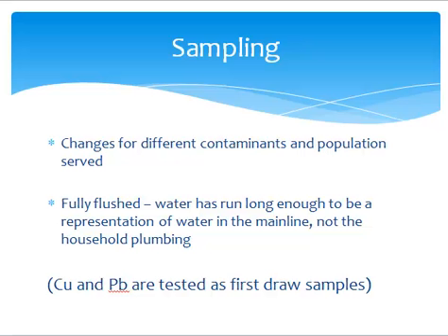When and how often a municipal source collects water samples is dependent on the contaminant and the population served. However, unless a sample is to be tested for copper or lead, the line is fully flushed before collecting the sample.